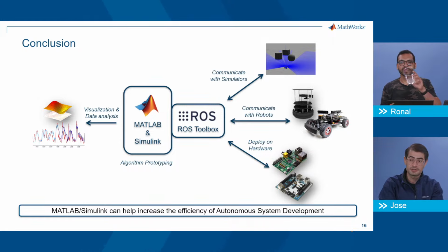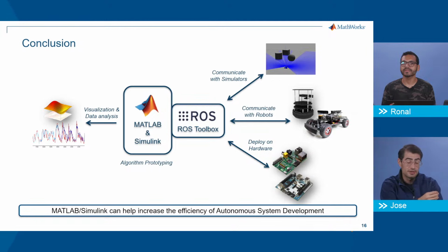We talked about ROS, and robots that are powered by ROS and how to interact with them from MATLAB. You can do it through scripts. You can interact with subscribers, publishers, with all of the sensors and actuators in your robots. Then you can also move on to Simulink. You can do the same in this modeling environment where you can actually generate your nodes, put them in your robot permanently if that's what you're looking for, and then test and debug and try things that way. Yeah, I think that about covers it.